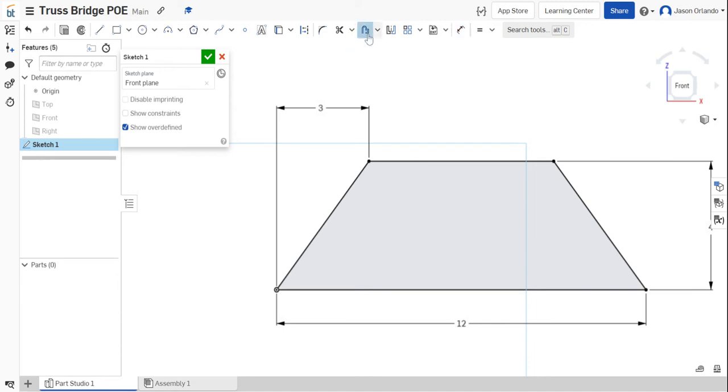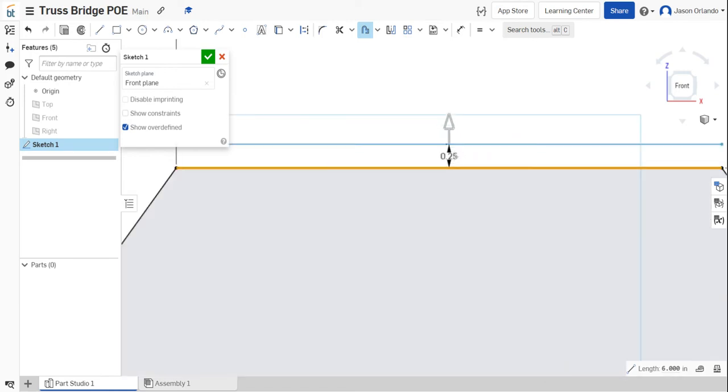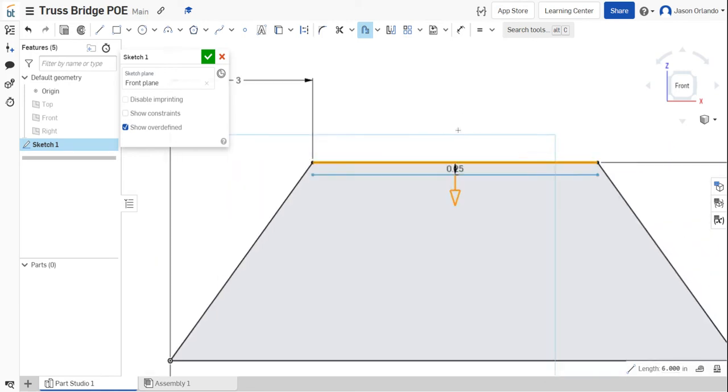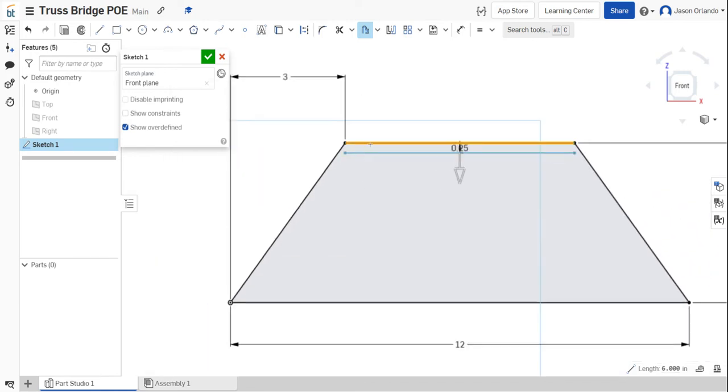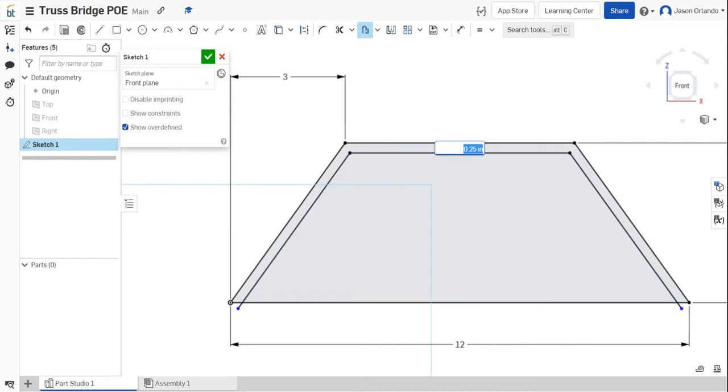Kind of an easy tool for creating parallel lines and creating that offset that you want is this offset tool. I can click on a line segment and it makes a parallel line and gives me the distance between them. If I click that arrow, it'll flip to the other side. And if I connect or select adjoining sides, then those segments will already be connected. So I'm going to go ahead and create a 1/4 inch offset on just those 3 sides. I'm going to hit enter to kind of say, yep, those are the ones I want.